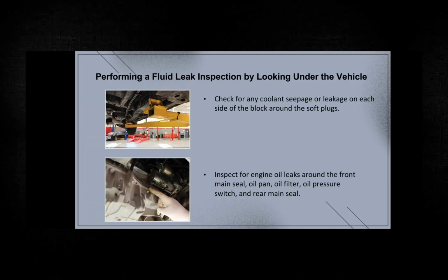Performing a fluid leak inspection by looking under the vehicle. First image, check for coolant seepage or leakage on each side of the block around the soft plugs. Inspect for engine oil leaks around the front main seal, oil pan, oil filter, oil pressure switch, and rear main seal.